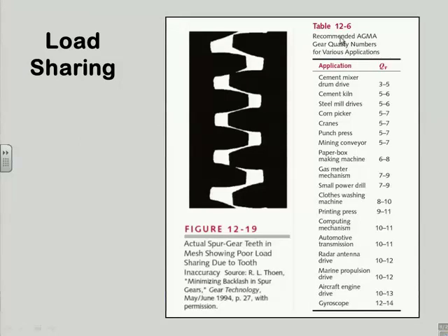And here they recommend, this is AGMA again, depending upon your application, they suggest that you need a gear of this level of quality. So at the very bottom, cement mixer drum drive: cheap, crummy gears that are going to live a hard life anyway, and it's not an accurate situation. I'm turning the drum so I can mix the cement. No big deal. No great accuracy required.